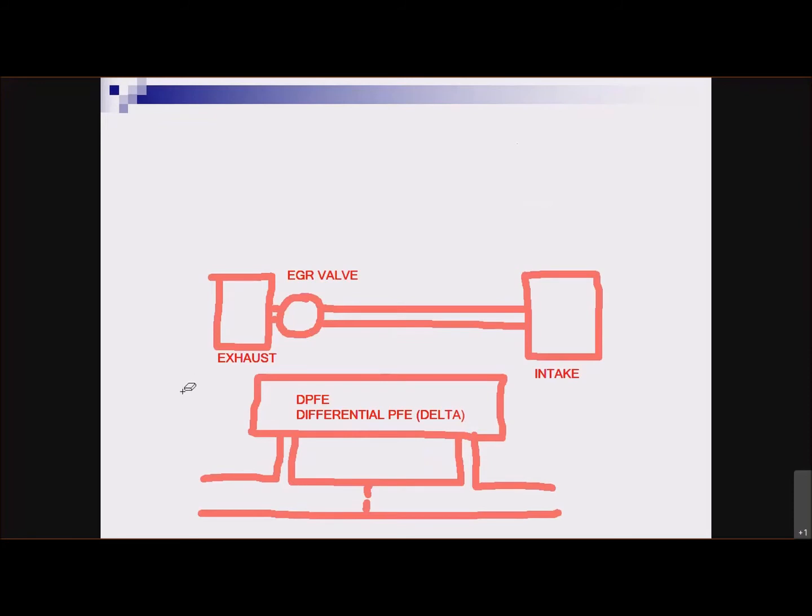So with the EGR valve closed, okay, the exhaust pressure comes in from the exhaust here, and it goes through that orifice, and the valve would be over here. I kind of drew that wrong. The EGR valve should be here, right? On the intake side. Talk about confusing, I know. So the EGR valve is sitting over here. This thing here. Doesn't look like much of a valve, I know.